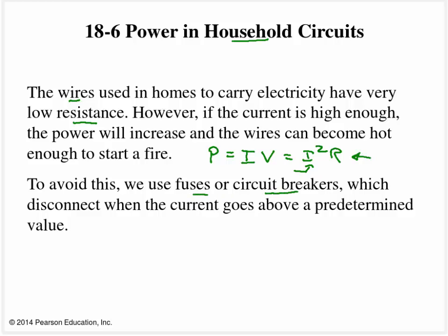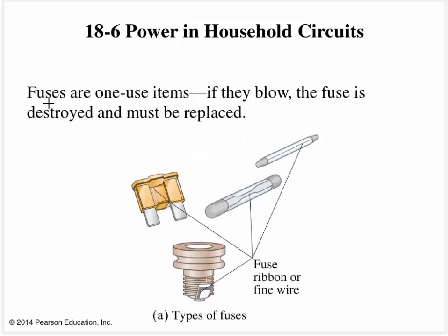So we use these things called fuses or circuit breakers, which is essentially going to say, hey, I'm going to put this wire into my circuit. So put some power source across this, and we're going to get current flowing through this wire. This wire in the fuse is going to melt once the current reaches some predetermined value, and once this chunk of the wire actually melts, then it breaks the circuit and current won't flow, melting the wires in our house that we don't want to catch on fire. Now the old-timey way to do this is to use fuses, where you'd say, hey, I'm going to hook this up past my power source, and once this current reaches, say, 1 amp, then this wire is going to melt and it's going to break my circuit.